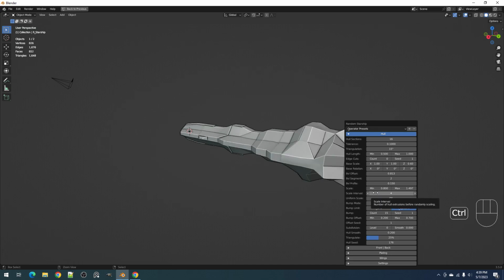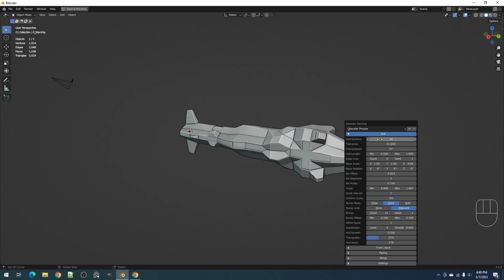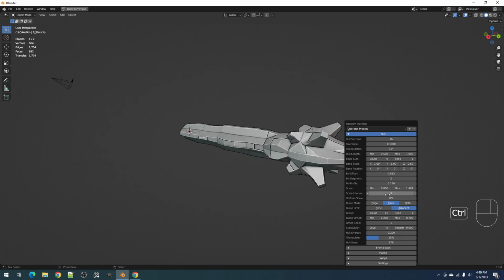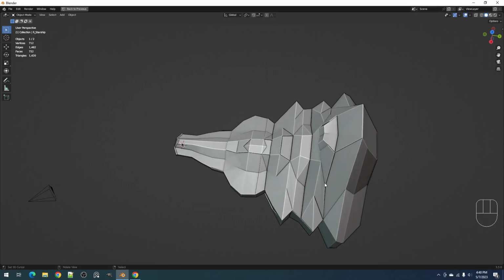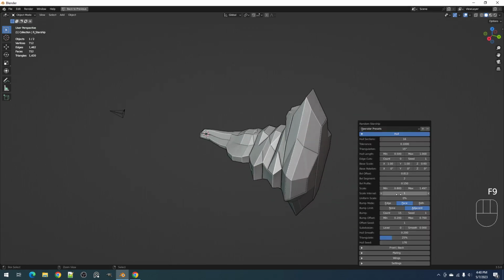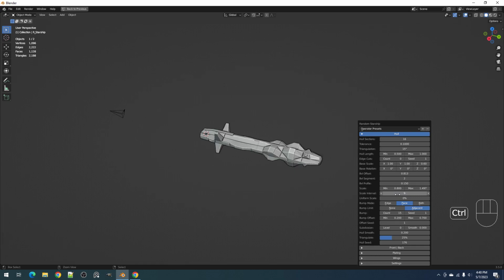So this means that, for example, in the 16 half sections that are being extruded, in every fifth number of that half section number, there will be a scaling. The scaling will occur for every fifth number in the 16 half section count. So essentially, avoiding this phenomenon here. That's the purpose of the scale interval. So for 16 half section, let's use 4.